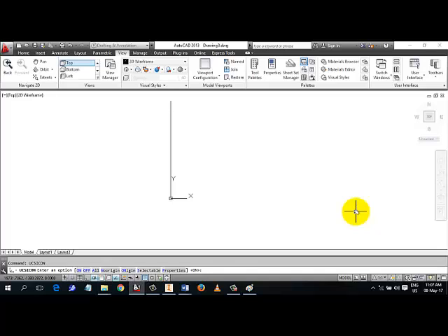There are many options. I told you AutoCAD gives options. What are the options there? On, off, origin, no origin, selectable properties. The one in angular bracket is what? On. So if you press enter, that means you want it on.